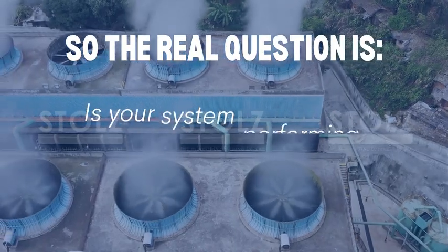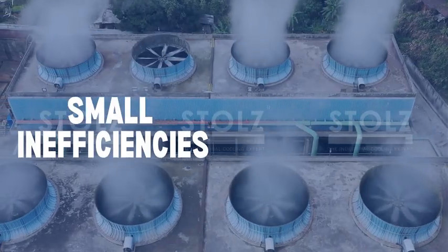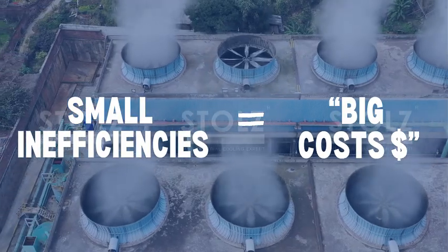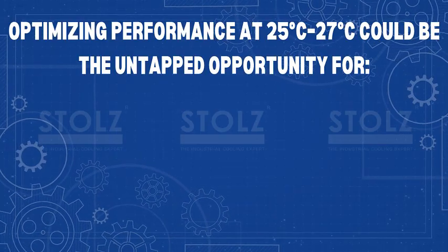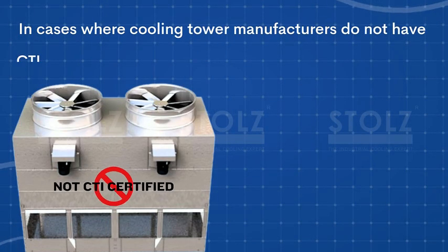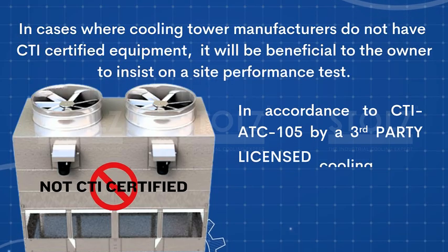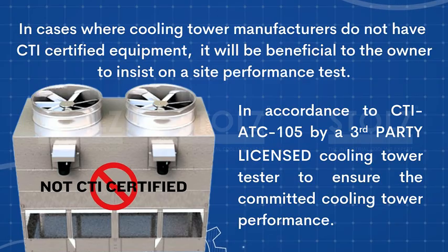So the real question is: is your system performing efficiently when it's supposed to be working the most? Because small inefficiencies in this common range can quietly lead to bigger energy bills and increased operating costs over time. Optimizing performance at 25 to 27 degrees Celsius could be the untapped opportunity for better system reliability, sustainability and savings. In cases where cooling tower manufacturers do not have CTI certified equipment, it will be beneficial to the owner to insist on a site performance test in accordance with CTI ATC 105 by a third-party licensed cooling tower tester to ensure the committed cooling tower performance.